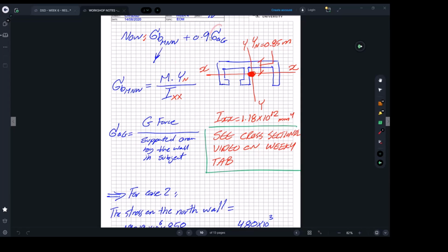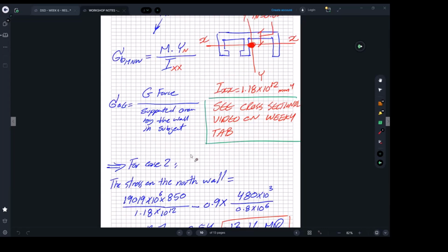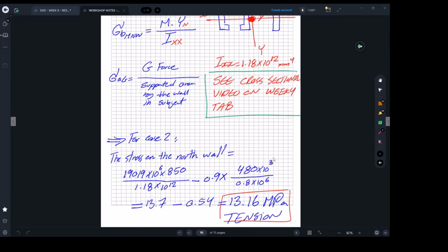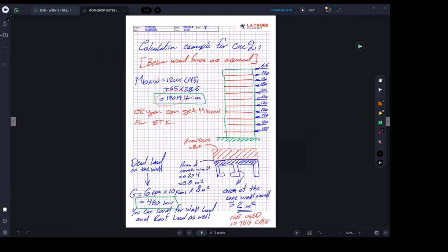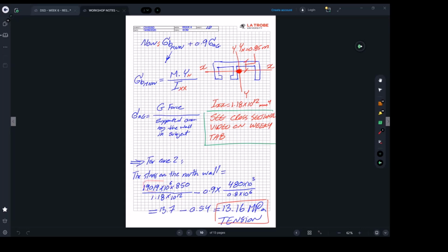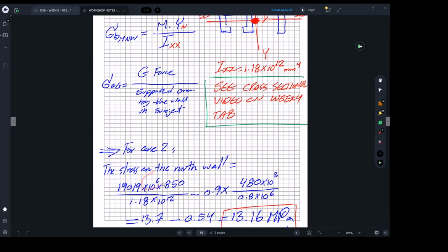And to calculate the axial stress, I'm just using this very simple mechanics of solids equation, which is the force over the supported area of that wall. Here, this line is showing you how I substituted the values, right? So this is the moment, what was it? Let me check. Yeah, it's the same as this. This one, I just took it here, and I've just changed the units.